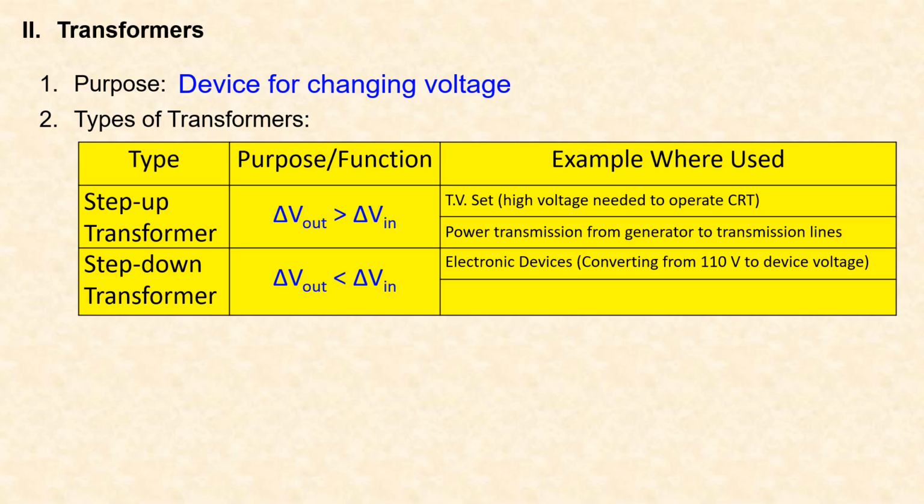You may need a rectifier to convert the AC voltage into a DC current, but you certainly are going to have to step down the voltage from the 110 to 120 volt electrical outlet to a more usable device voltage somewhere on the order typically of 12 volts or less.